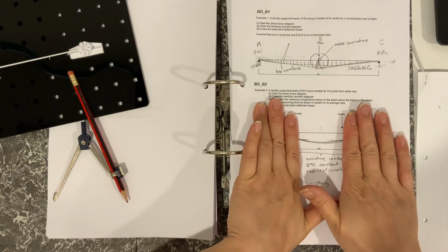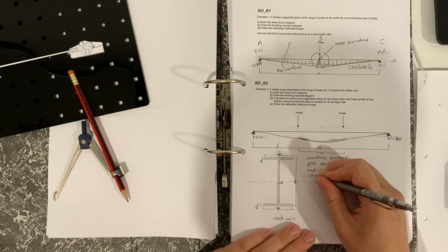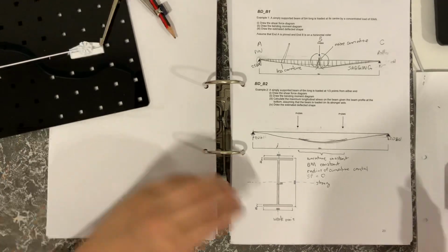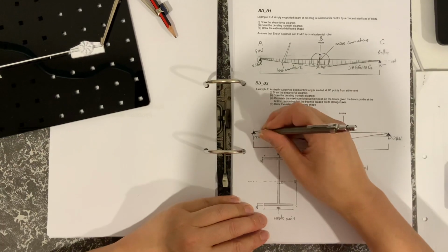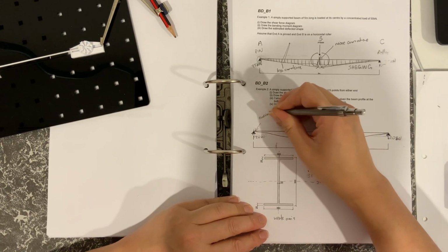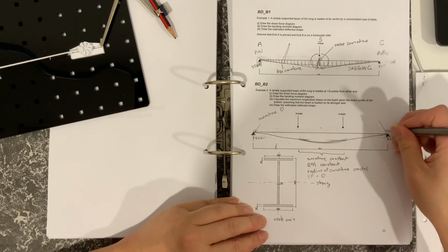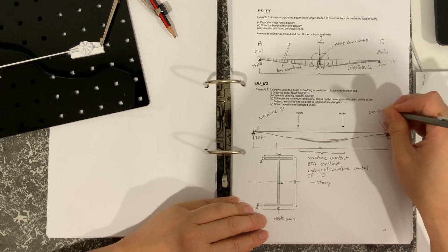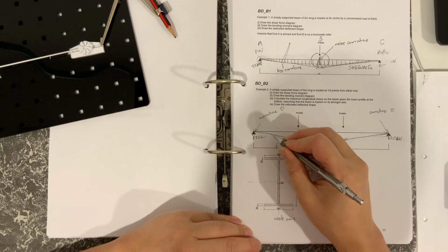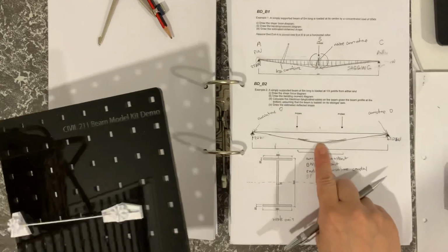between those two points here, because the bending moment is constant, and then we would also say the shear force would be equal to 0, which it is. And then here the curvature would be 0 because it's at the end, so curvature 0 as it was there because it's a pin, and along there again curvature 0. And then here there would be some curvature, but not as much curvature as there is here.